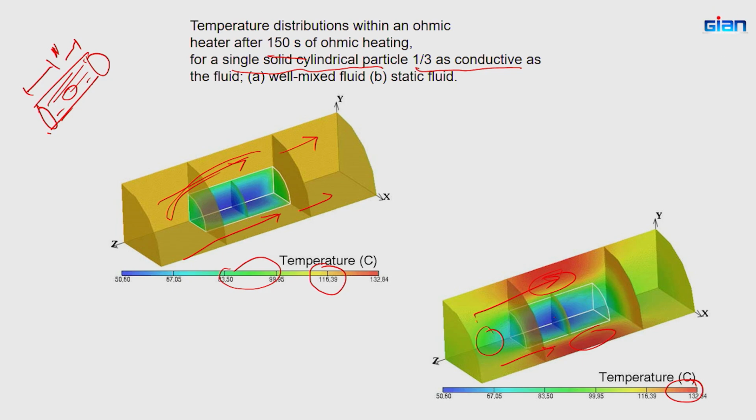So the point here is, in the ohmic heater, if you have a change in electrical conductivity between the liquid and solid, you could have different heating happen in the liquid and solid, and then you are going to have non-uniform temperature distribution. When you have non-uniform temperature distribution, that means you are not going to heat the entire mass the same as we originally thought possible. That means you are potentially going to have microbes there. It is potentially a food safety problem.